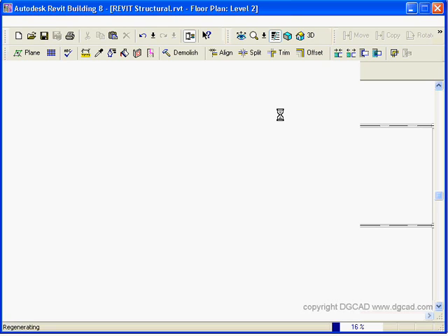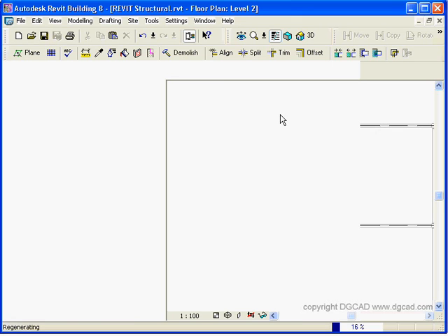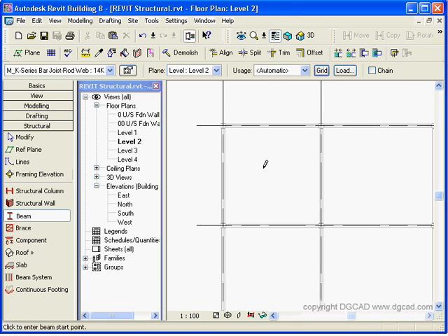And later we'll show you when you want to load or place a sloped joist, we will have to create a sloped reference plane, and then we draw our sloped joists on there. So there's our joists brought into the system.